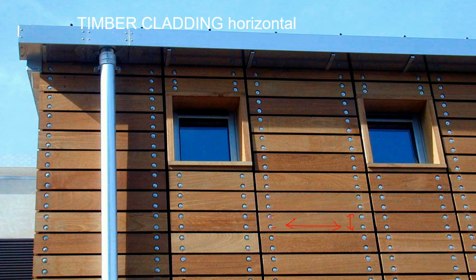So what we tend to do is, and I'll draw up at the top here, you would have your board. Wow, that's an awful drawing. Right, we would have our board like that. It's truly awful. And the screw would come through the board like this into the backing, and we would put a washer there and then the dome head of the screw. So the board could move about a little bit, and this little gap here would be enough to take up that slack.